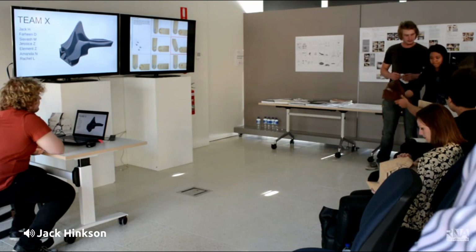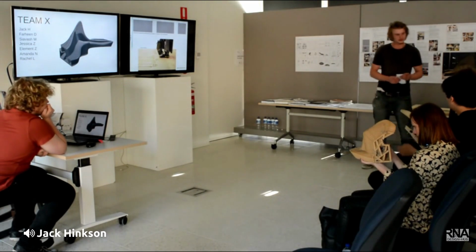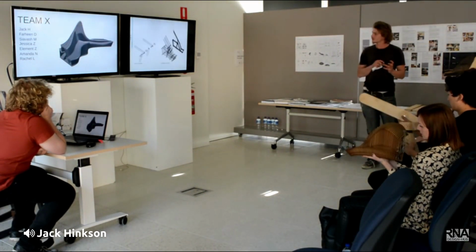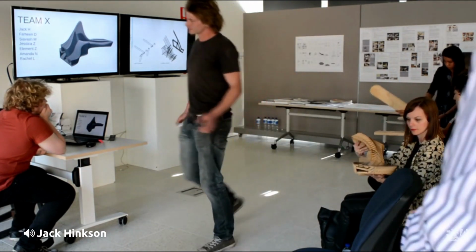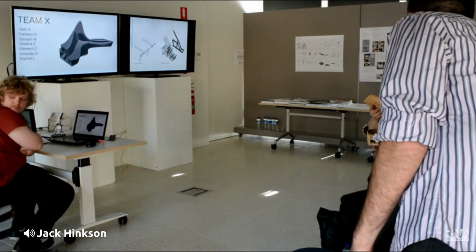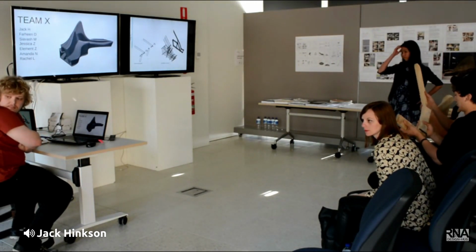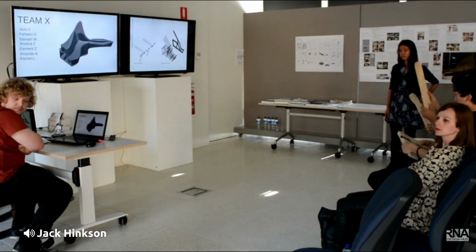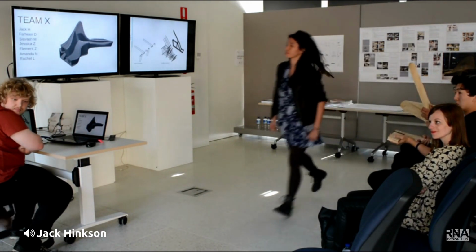For our first one-to-one prototype, we used these rubber inserts which gave flex to shearing forces. We incorporated them into this one-to-one design here. So in these joints, here and here, we have these rubber inserts which spring load the structure and bounce it back.